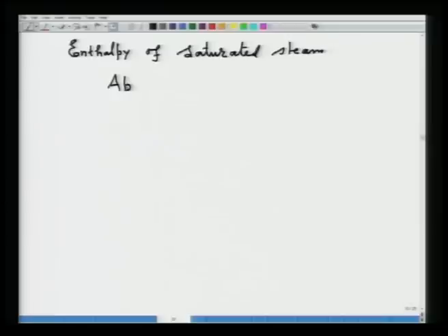Pressure surrounding the gasifier is 740 millimeter, and if you convert, it comes out to be 14.3 psi. So, the absolute pressure is equal to 30.8 plus 14.3, that is equal to 45.1 psi.